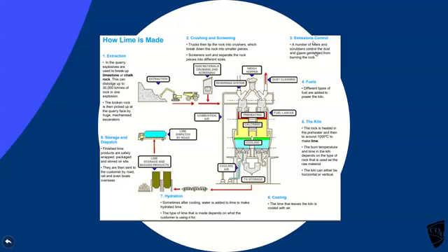You've got to control the stuff coming out the top, so we actually have scrubbers on the top to keep the dust inside. You throw in some fuel to get it heated up, and it goes bubble, bubble, bubble to its 900 to 1,000 degrees, and then it cools down here, and out comes the lime at the bottom, where you cool it a little bit, and it goes off to storage, where it can then be dispatched to whoever's going to use it to make their various types of lime.